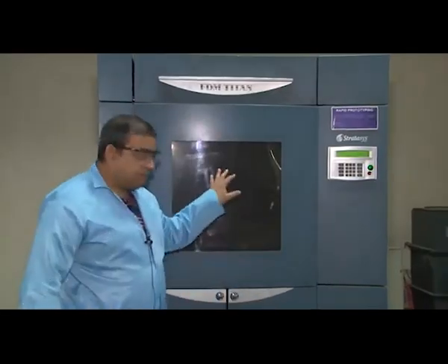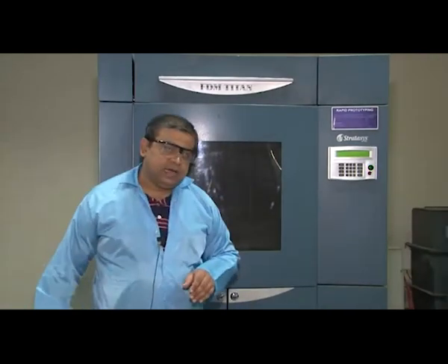The whole idea is that if there is any complex feature or shape as a CAD file which is available, the system tries to section that particular CAD file into small elements. And each element is deposited by means of plastics, which are typically two in kind. One is either polycarbonate or ABS plastic, and this particular machine has the capability of handling those plastics.